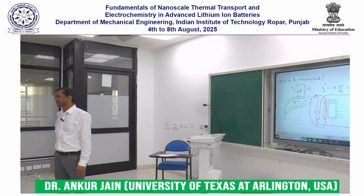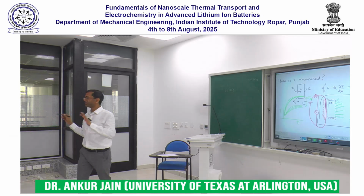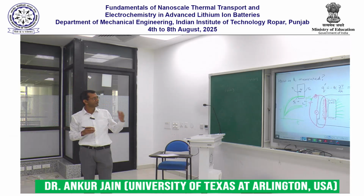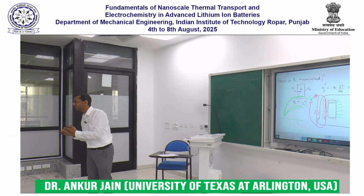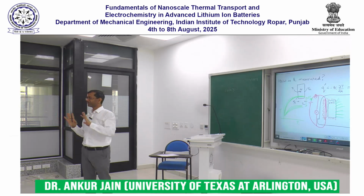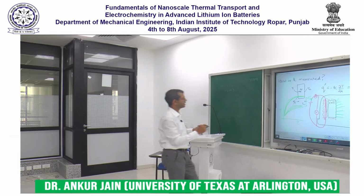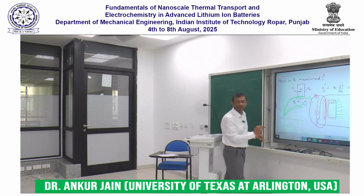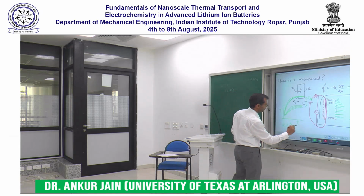Sure, yes, absolutely. Strictly speaking, theoretically speaking, steady state is reached at infinite time. You don't have infinite time on your hands. You have to graduate and go, right? Therefore, you have to figure out some other criteria to be confident that you have more or less reached steady state. Typically, the criteria is to say that I do not want to see more than plus or minus some x degrees C fluctuation in temperature over y seconds.